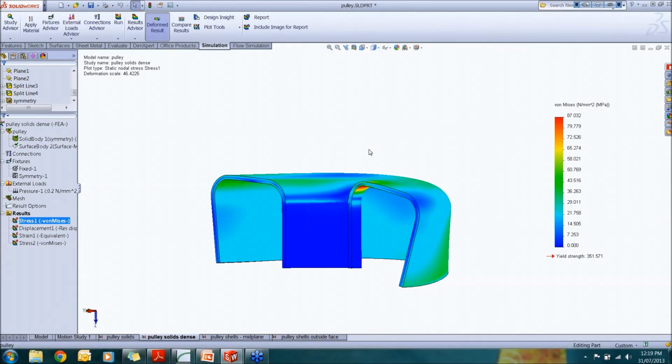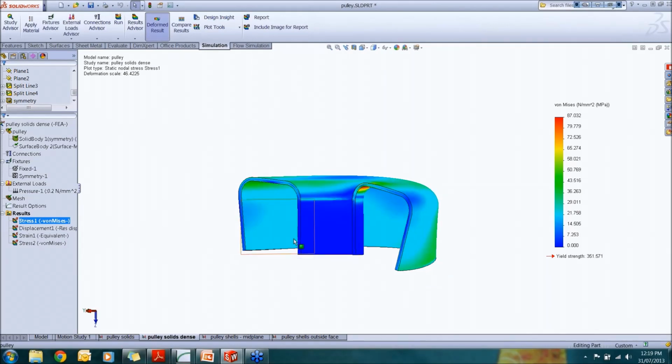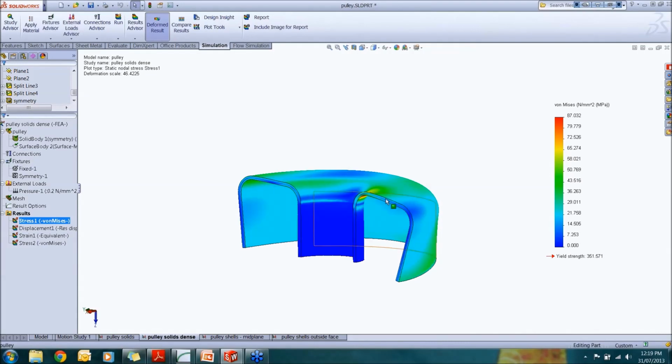So what would be the solution if we really want to capture the right image of the actual model's stress and strain result? We can simply say we want 3 faces, 1 on top, 1 on bottom, and 1 in the middle, and avoid the other elements through the thickness and see the result there.